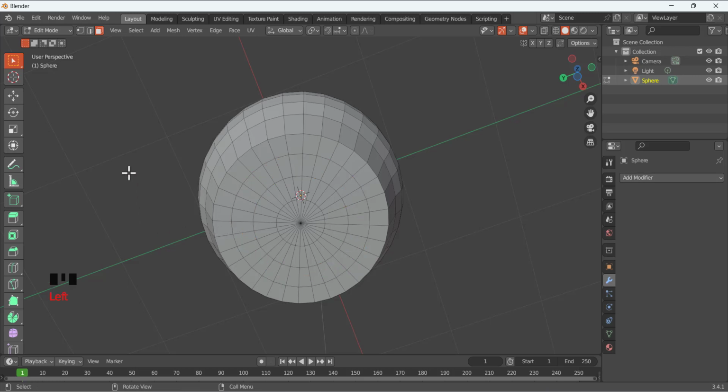So what is the shortcut if you want to select all of these faces which are in some type of pattern? How can you do that? You press Alt on your keyboard and then select this face. But make sure you are near to this edge. Like that. Now you can see, in one click, basically two clicks, we pressed Alt.